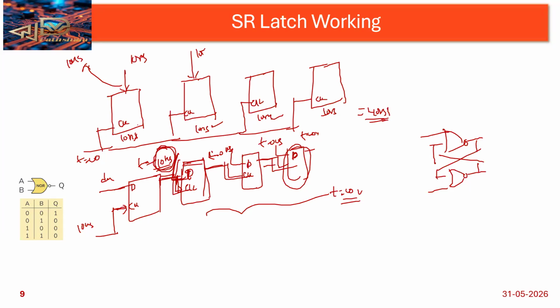Here the clock is every time there, right? See, in synchronous, the 4-bit up counter, every time the clock is there. So here only one clock we are giving, and then the next one is given to the clock of this one.